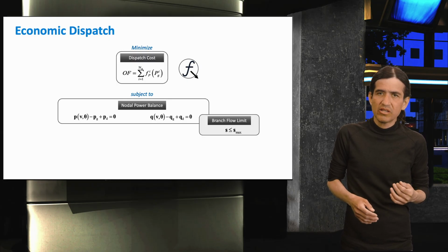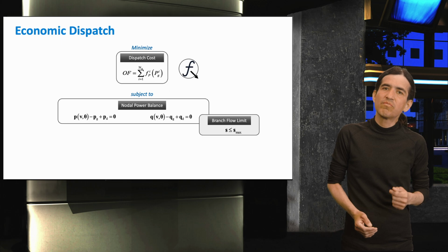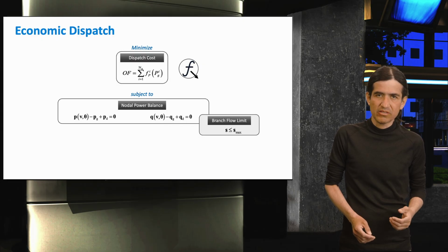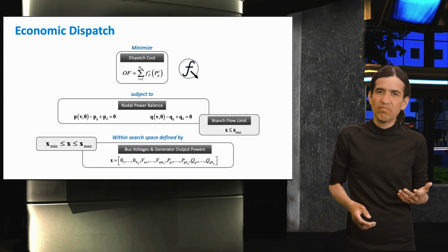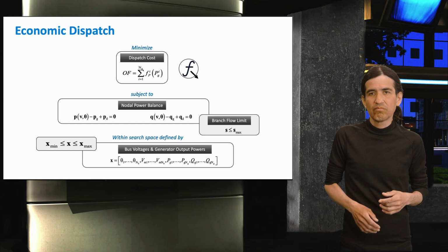Equality constraints enforce power balance, like total generation equals demand, possibly including losses, while inequality constraints represent operational limits, such as generator capacities, ramp rates, and network limits. In addition, search-bound constraints define the minimum and maximum allowable values of decision variables, restricting the feasible region.